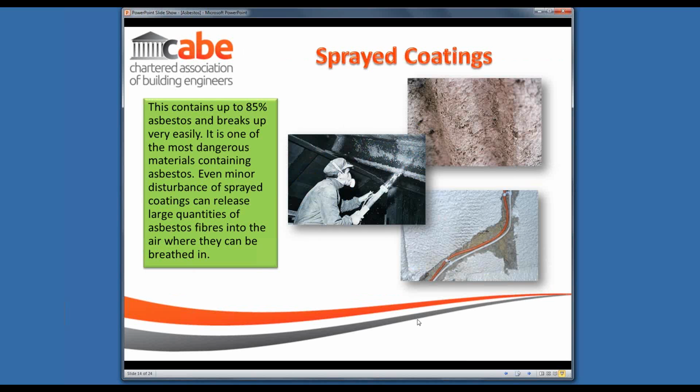How dangerous would it be, for example, if you wanted to put in an extra light fitting to create a hole in an Artex ceiling? What would the risk be there? Yes, obviously with anything that contains asbestos there is always a risk in carrying out work.